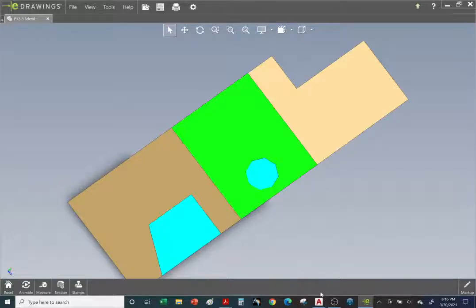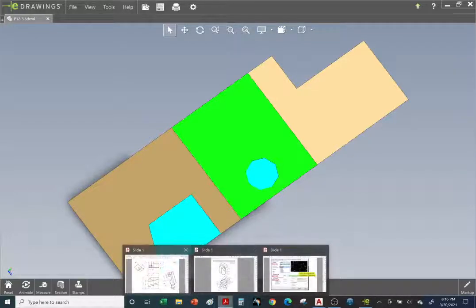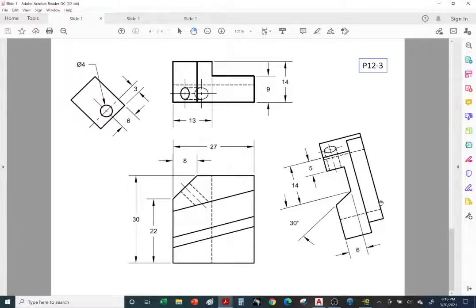All right, so let's go ahead and complete that one. Let's take a look at the answer key. We're going to cheat. Okay, so we got everything here on the right. I think we have everything. I'll double check and see if we didn't miss this object line. And we have this hole that lines up with the hole here, right? And this vertex lines up with this vertex and this vertex with this one. Notice it's all parallel to the axis or perpendicular to the axis of the hole. Okay, so let's go back to AutoCAD.